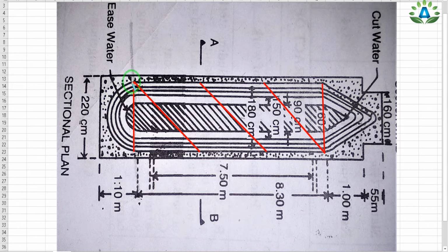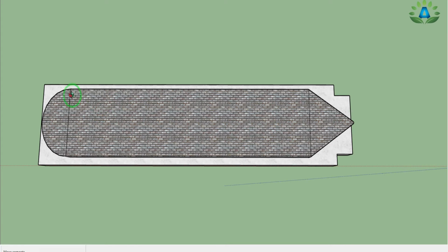So we know that if we multiply the area by the height, then we will get the total volume, and we have the area of the semicircle, pi d square by 8. So that means we have to calculate the diameter for each of these semicircles. So when we view this first footing from the top view, it will look like this. That means we have to calculate the diameter from this side up to this side, and we can clearly see that this diameter is equal to the width of this first footing.